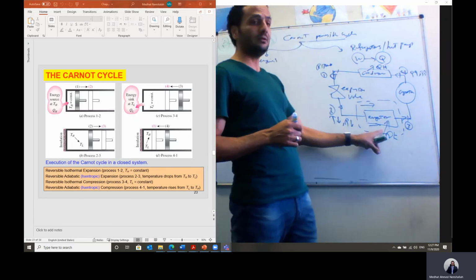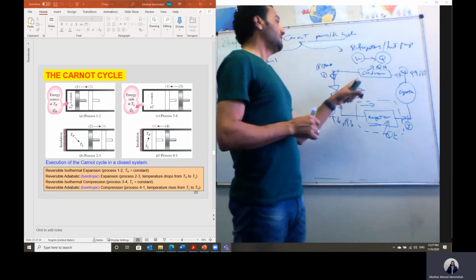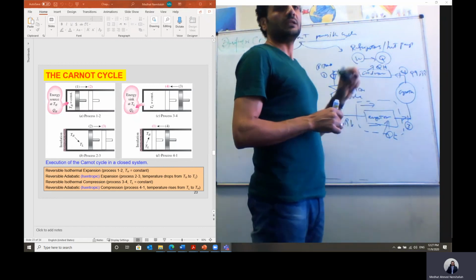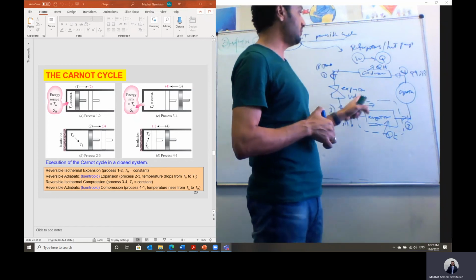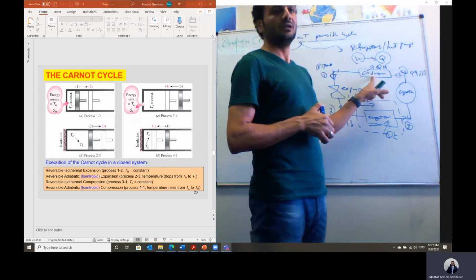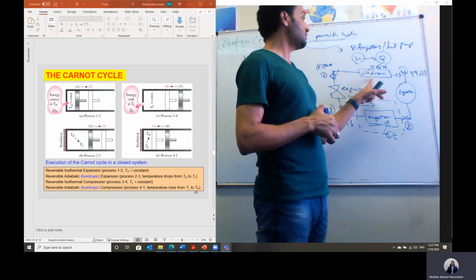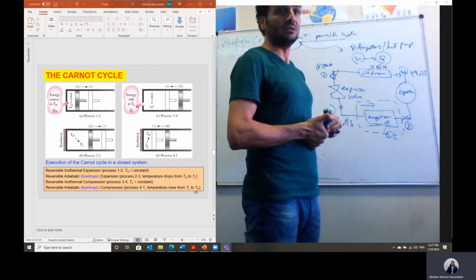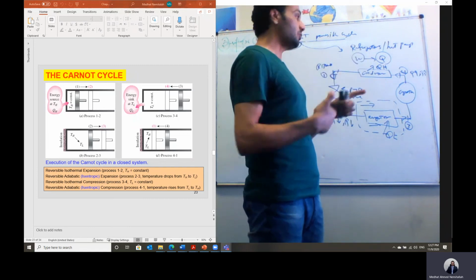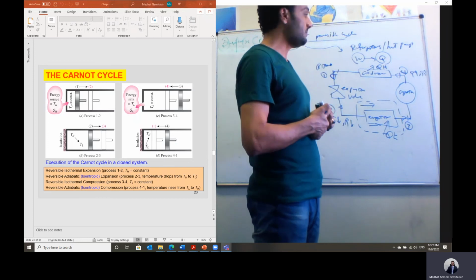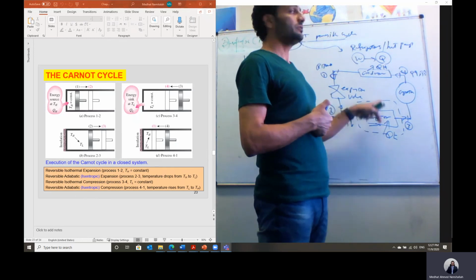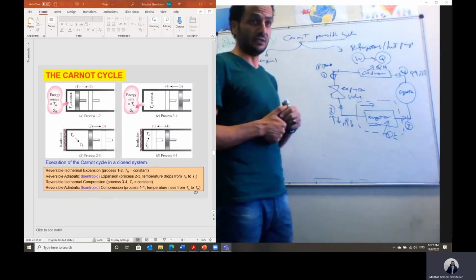So here heat is added at low temperature and rejected in the condenser at high temperature in case of the refrigeration cycle. In case of a heat pump, what we need from the system is Q high, like using the air conditioning system as a heating system. We just flip it to have the condenser inside, then we will have Q high inside. So we absorb the heat from outside and reject it inside in this case.